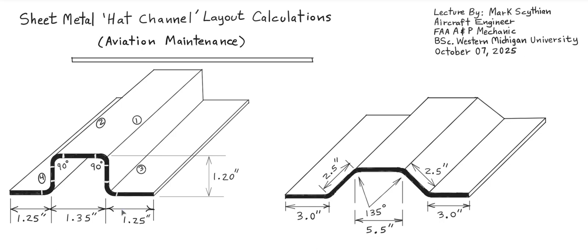So all we're trying to do is invoke or implement these bend allowances with a sheet metal brake. And so that is a controlled bend, which then implements a controlled bend without cracks or stress risers.